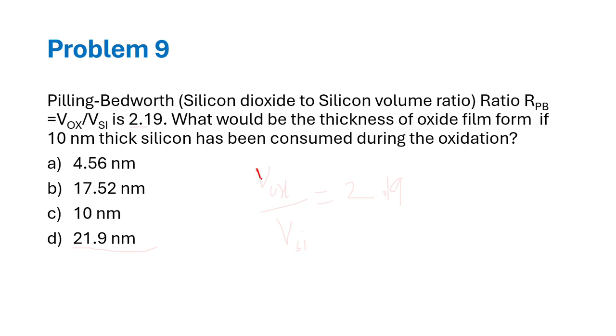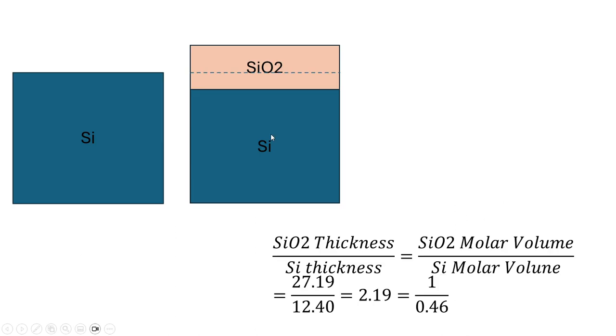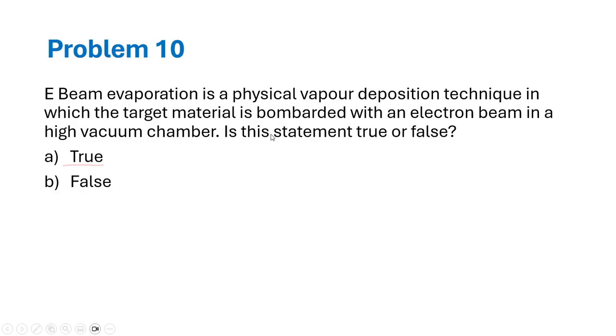So there were other evaporation methods as well, thermal evaporation and e-beam evaporation, right? In e-beam evaporation, we have a crucible with the material that we want to evaporate. We'll have a substrate in line of sight of the crucible. Then we will have an electron gun.